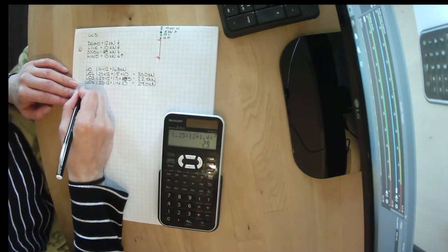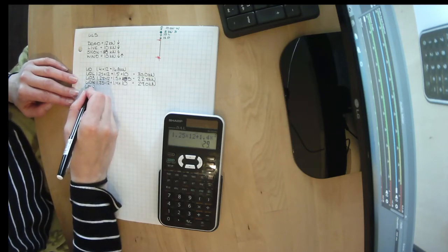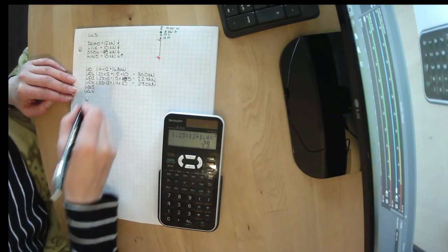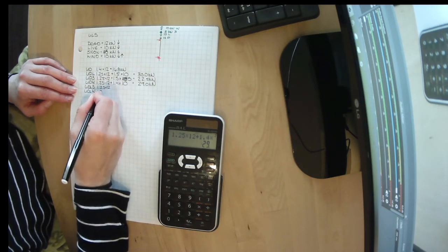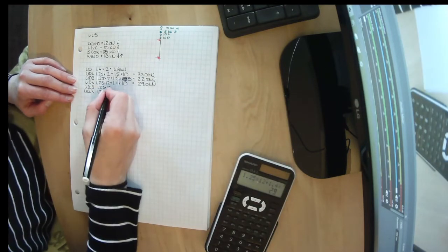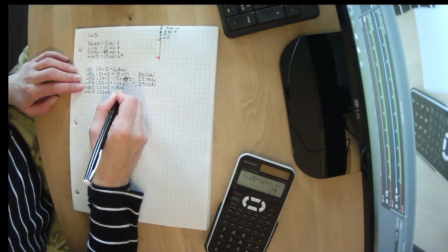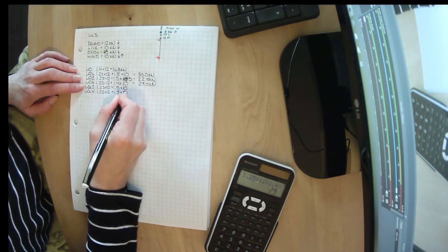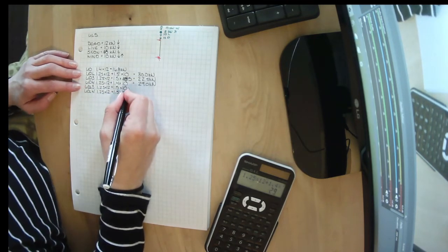We can have, let's focus on live as the principal. With live as the principal, we could have snow as the companion, or we could have wind as the companion. So 1.25 times our 12 kilonewtons of dead load, and that doesn't change for either of those, plus, so live is still our 1.5 times 10, and our snow load is a companion load in this situation.